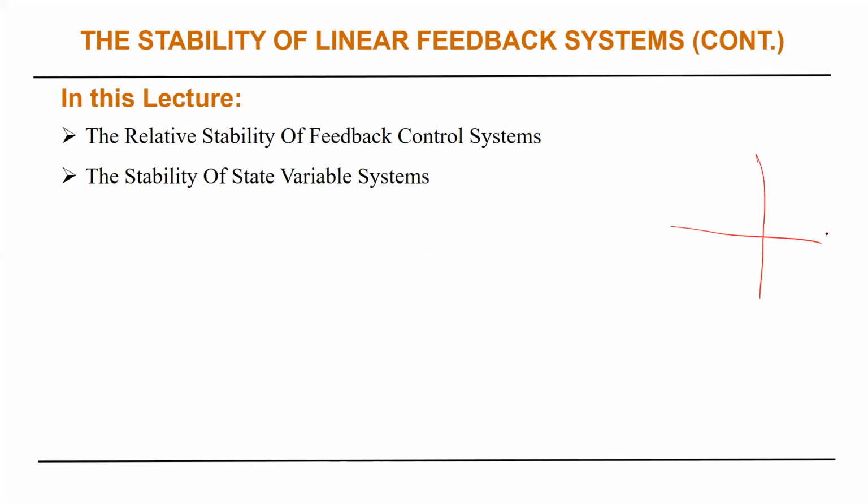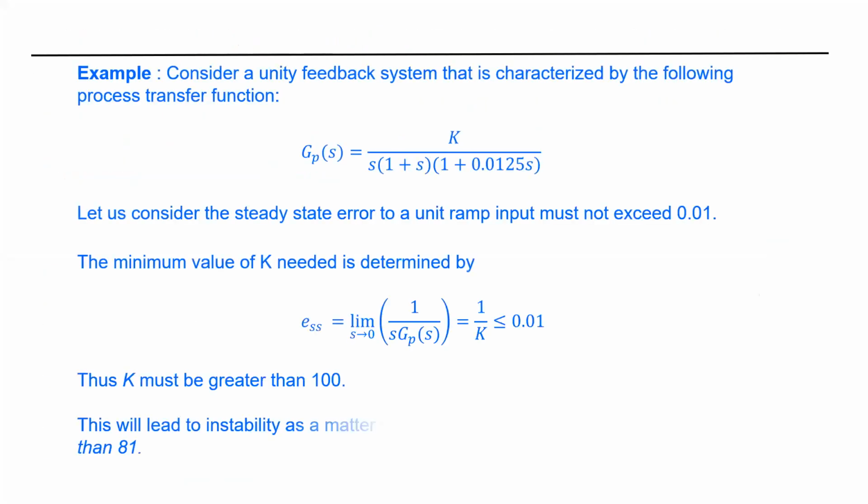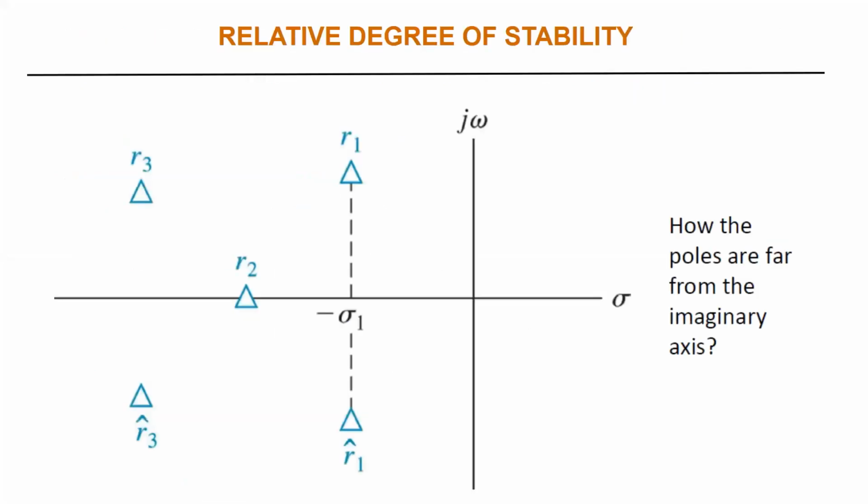Simply in here, suppose I have this system. Which one do you think the poles of the system? All the cases are stable because the poles are in the left half plane. But which one will have more oscillation? Which is nearer to the imaginary axis. Exactly. As you move toward the j omega axis, the degree of stability will be less.